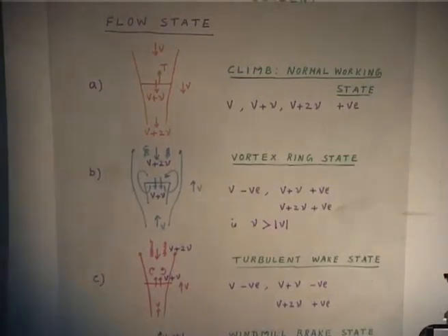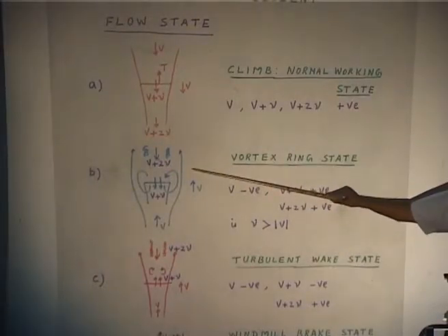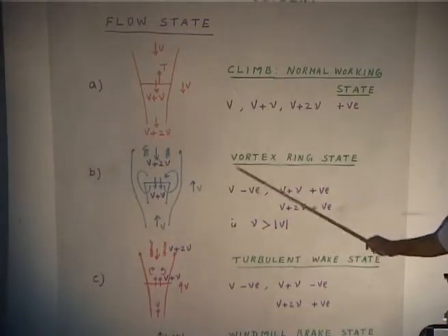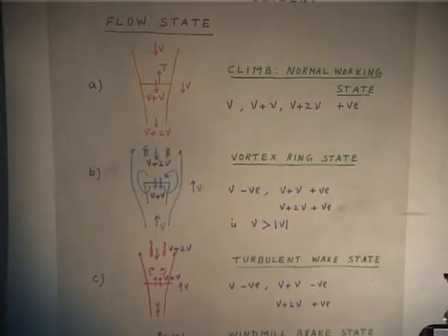Now you see in this state the helicopter will have a lot of vibration because the vortex will come, it detaches. If you sit in a helicopter, when the pilot is coming vertically down, or even sometimes when he comes at some angle, you will find a lot of vibration will be there. Now in this state, the flow is still downwards at the rotor disc.